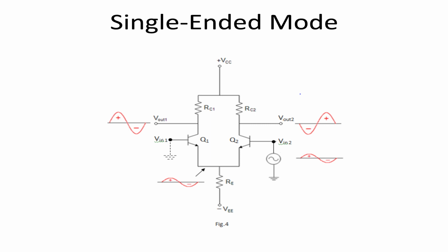Whatever operation is performed inside the circuit, we actually replace it by this block diagram. Every time we are interested in drawing a differential amplifier, we will use this block diagram, and at the output terminal we get V0, which is always equal to the gain A multiplied by the difference of the inputs. Whatever output we are getting, that is V0.